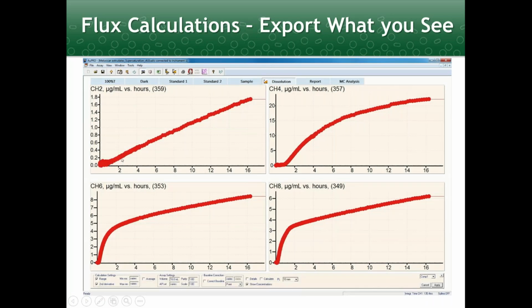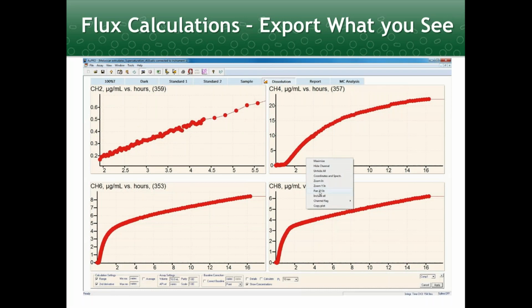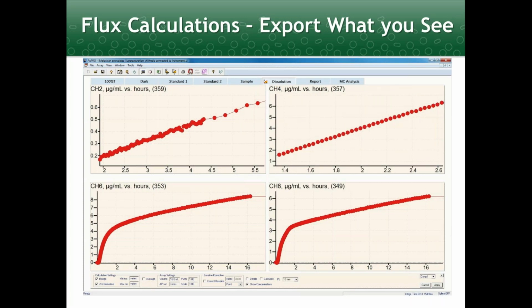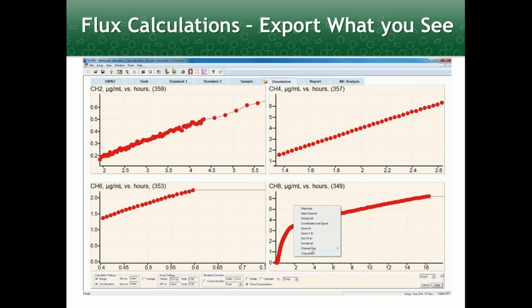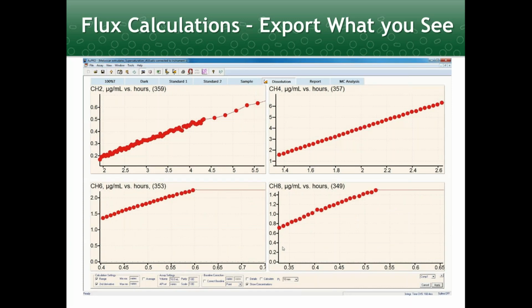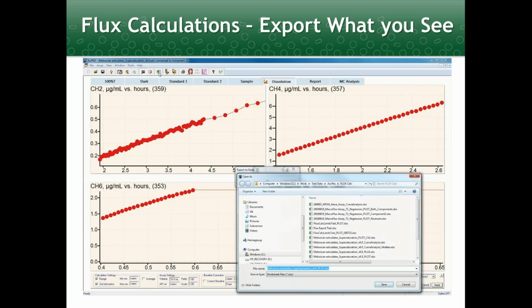It can be accomplished by using the available zoom in/out tool of the software. So first, select the required linear interval, which can be individual for each channel. So right here, a particular interval is selected for all even channels, which represent the receiver chambers in this case. And then exporting context data to Excel. So only a portion of the data is exported. It can be easily fitted by a straight line to calculate flux.